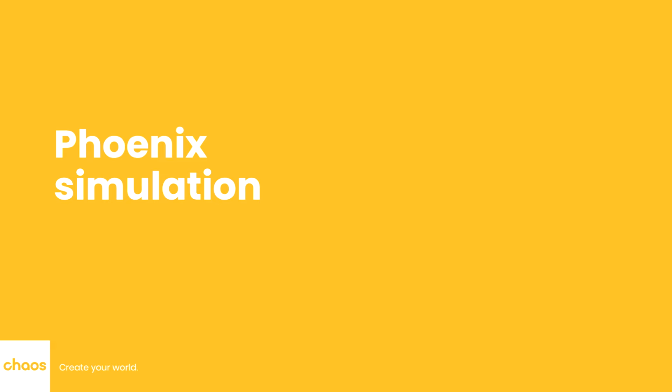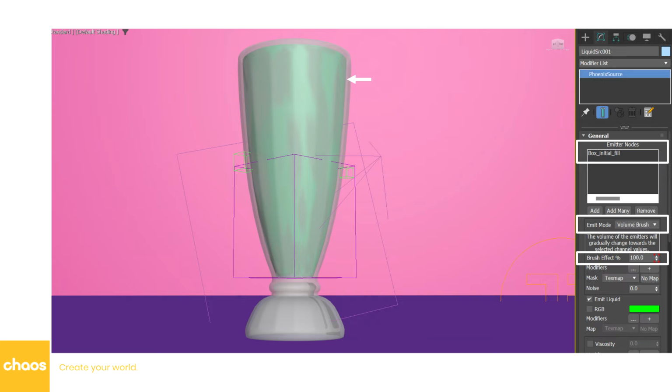With the completion of the rigid body simulation, destruction, and bullet time effects, we now have the necessary elements to integrate them into a fluid simulation using Phoenix. Let's start by creating a liquid source and adding the box initial fill geometry we just created in the emitter nodes. Instead of using surface force mode, switch to volume brush. This will brush out the volume with liquid.